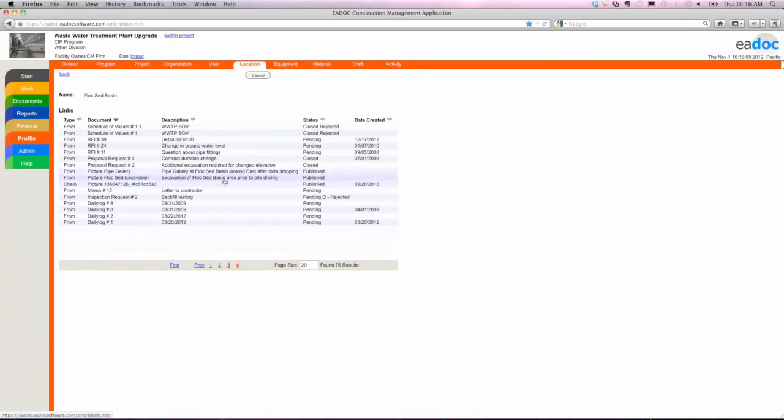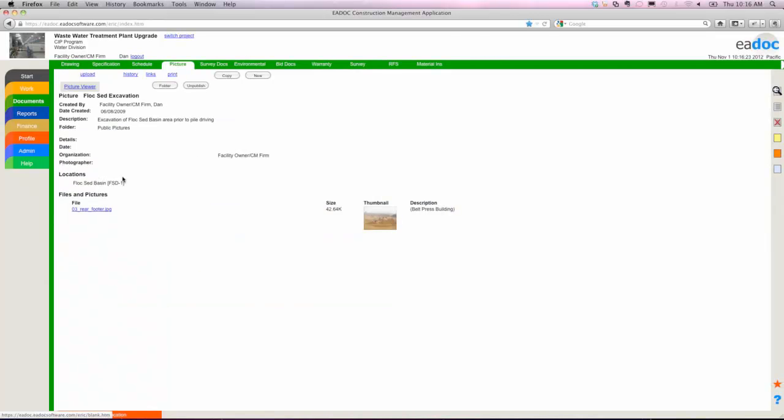These standards are still new in terms of construction industry standards, and they're still being adopted by several different organizations. There's a lot of federal agencies that are pushing some of these standards. Army Corps of Engineers is one, GSA is another, and one of them is COBIE, and that is the Construction Operations Building Information Exchange. And what this one does is it defines the format, how to track that electronic data.